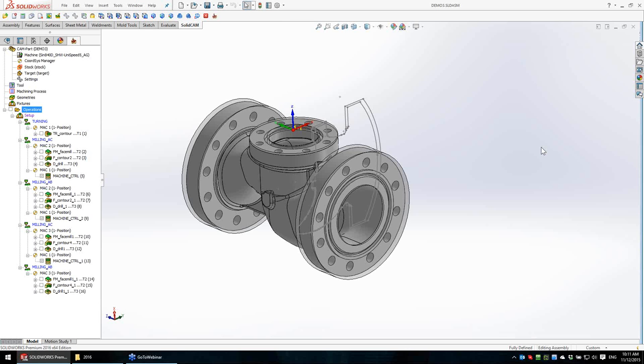But nothing different than how you worked in the previous way, on a 3-axis machine: a part, and you work with one coordinate system from the upper side of the part. You continue to work with a second coordinate system, Mach 2, position 1, on the lower side of the part. And you get 2 different coordinate systems in the G-code. We didn't change anything in the G-code. Also in the previous versions, you got the Mach number when you changed it. The problem was only in